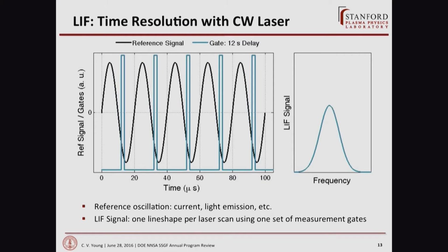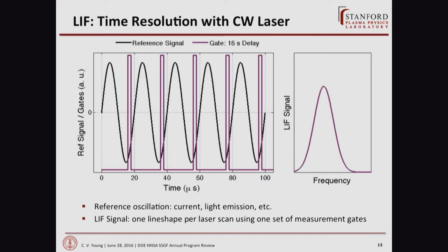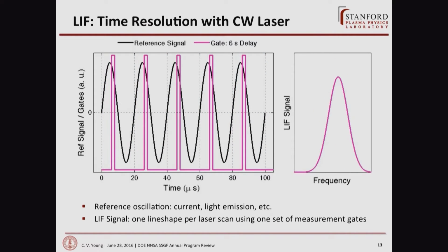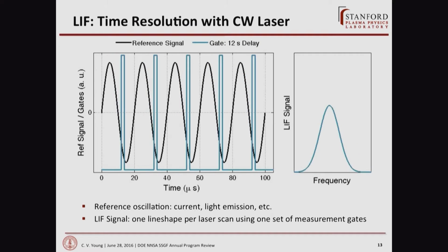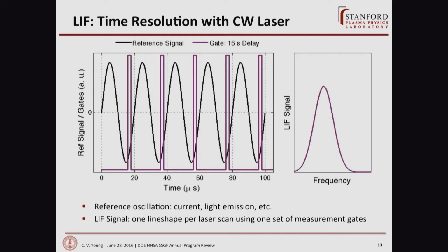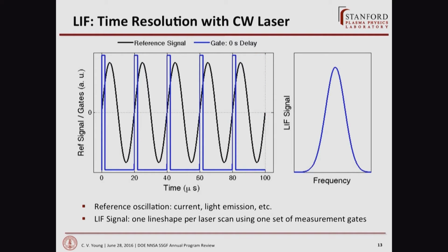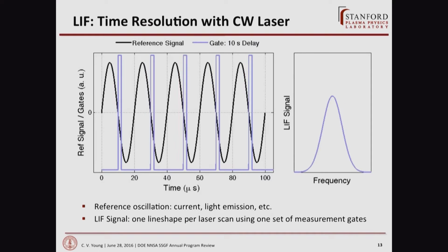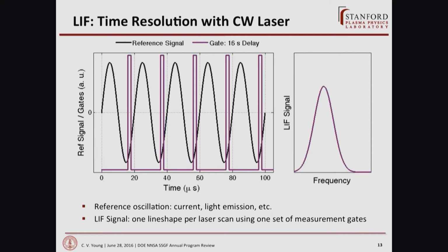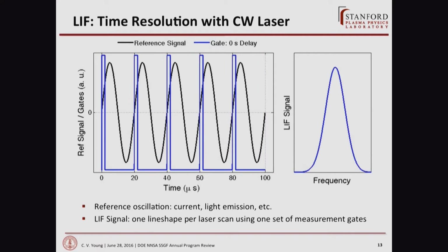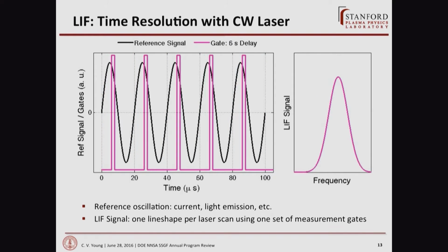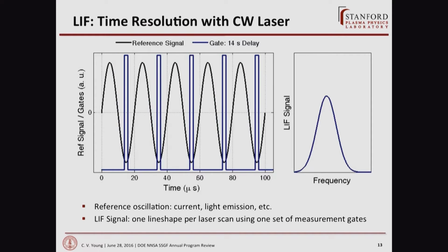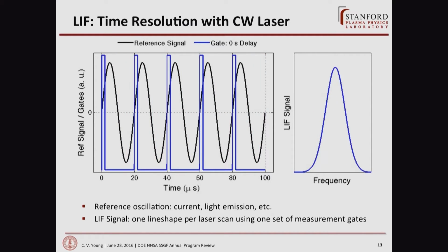So in the discharges that I used, like a Hall thruster, you can look at the discharge current. And sometimes these instabilities or some dynamic properties arise where we get an oscillating signal, like in the discharge current. So rather than collect fluorescence light over all time, which would give you a time average measurement, the goal here is to really restrict the time interval over which we collect the light and sort of throw out all the other light that's occurring outside of that target time window, and then only send that into the lock-in.